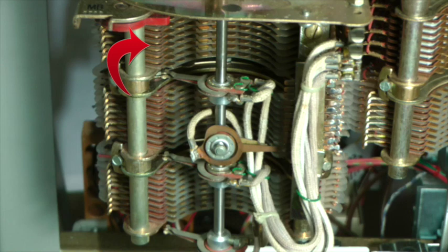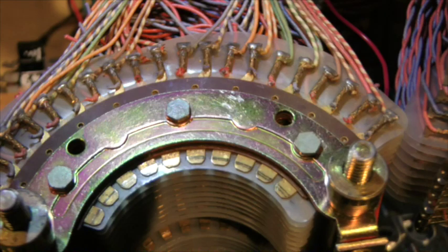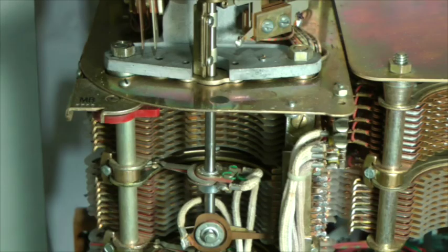Mounted at the bottom of the line finder switch, there is an arc-shaped apparatus called the bank assembly. The bank assembly is not actually part of the line finder switch, but when a line finder is mounted on its shelf, the bank assembly is bolted to it by these two threaded rods. These threaded rods protrude through the line finder frame and are secured to it by these two nuts. So the line finder and the bank assembly act as one functioning unit.